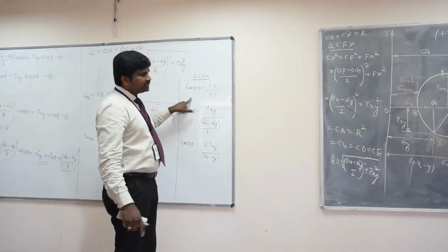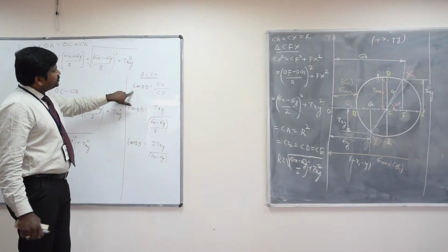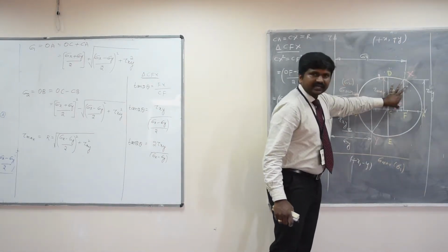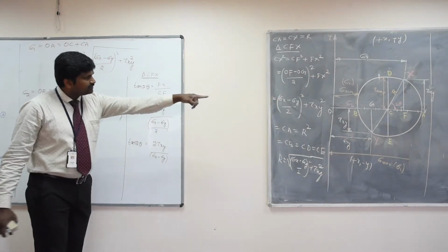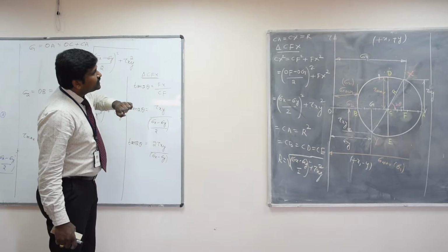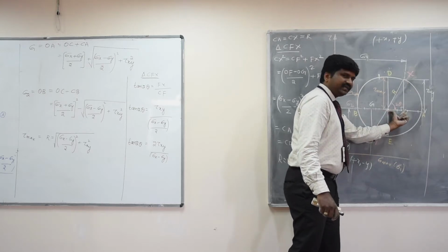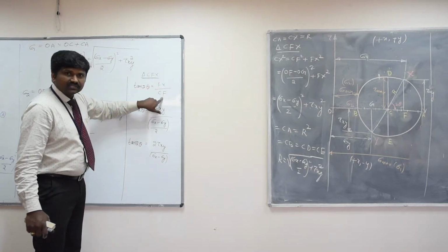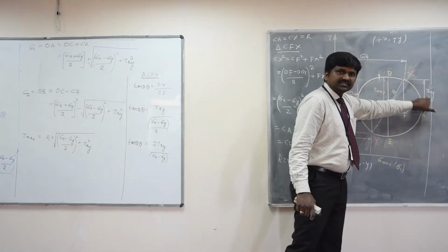Now coming to the determination of the angle of the plane where the stresses are maximum and minimum. We use the triangle CFX, which is again a right angle triangle. From this right angle triangle, we write tan 2 theta. So tan 2 theta is equal to, from the diagram, vertical by base. The vertical is Fx and this is the base, so it is Fx by CF. So what is Fx? Fx is equal to the shear stress tau xy.